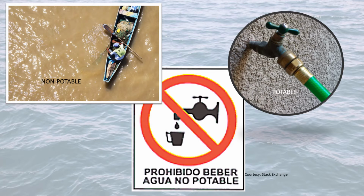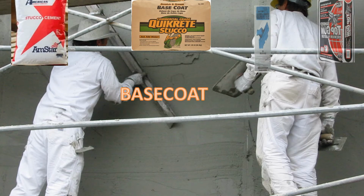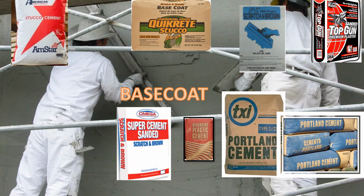Base coats. They come in a wide range of options and preferences that are often dependent on regional weather, availability, or maybe just what you're used to. While you may be given options, you do need to know some basic rules. Some products are basic cements. Remember, we called these common cements. You will need to add lime or plasticizers to make them workable.